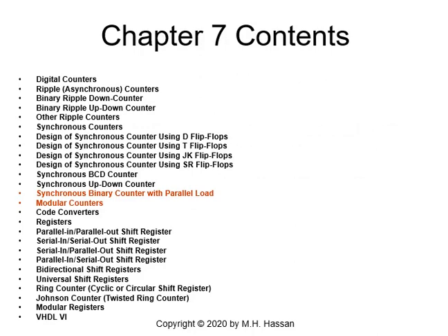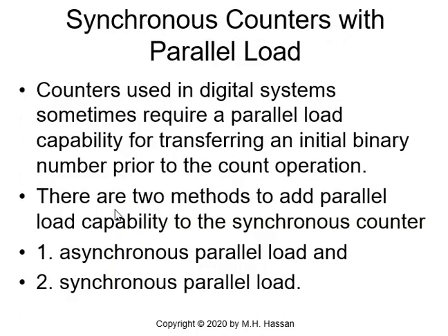In this lecture, we will cover synchronous binary counters with parallel load, and also we'll talk about modular integrated circuit counters. Synchronous counters with parallel load: counters used in digital systems sometimes require a parallel load capability for transferring an initial binary number prior to the count operation. There are 2 methods to add parallel load capability to the synchronous counter: asynchronous parallel load and synchronous parallel load, and we will talk about both.